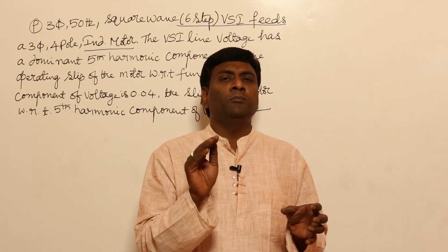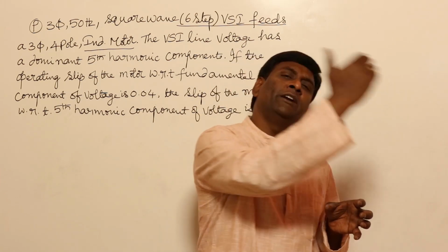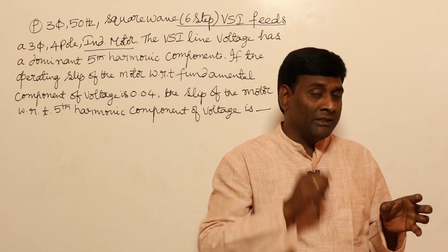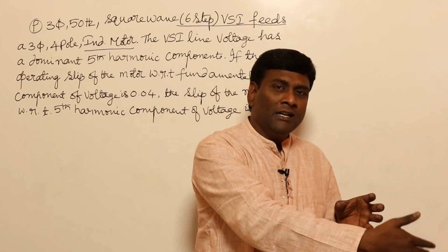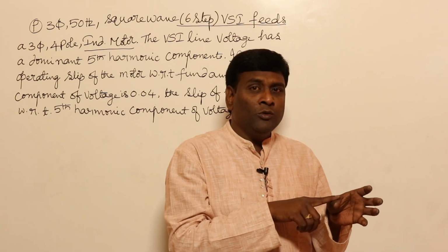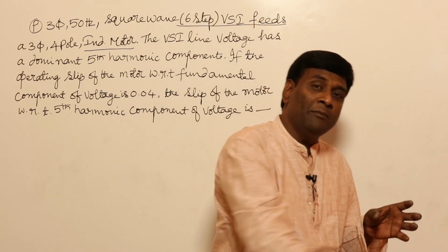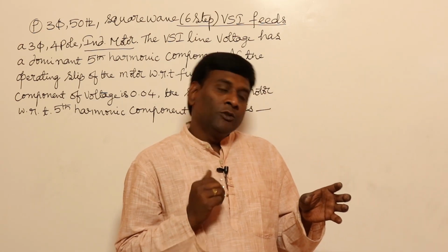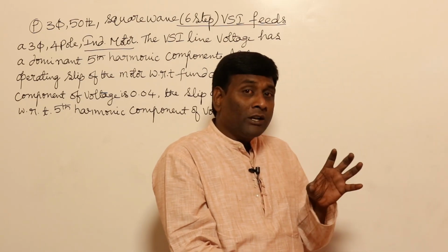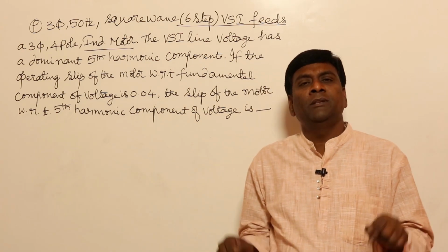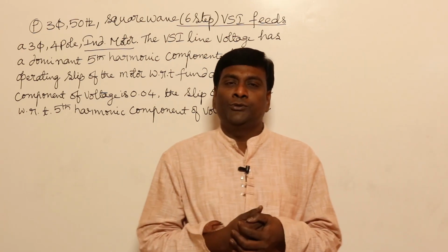Yes. For example, the seventh harmonic component is rotating in the same direction with 7 times synchronous speed, or synchronous speed by 7, both will be there. So the rotor will rotate at 950 only. For example, my stator mmf 7th harmonic is rotating in the same direction at 7000 rpm. The rotor is rotating at 950, then also relative velocity will be there. Because of that, induced voltage will be there, currents will be there, torque will be produced.